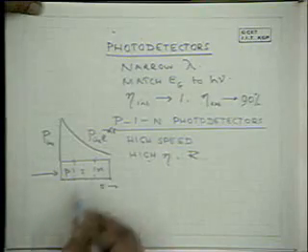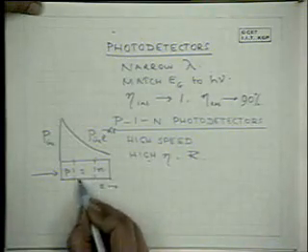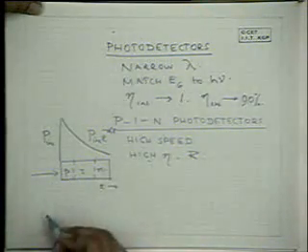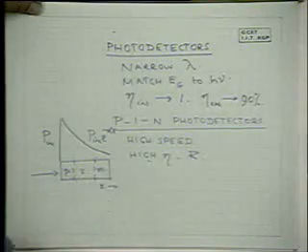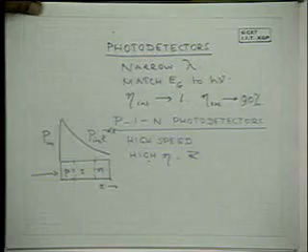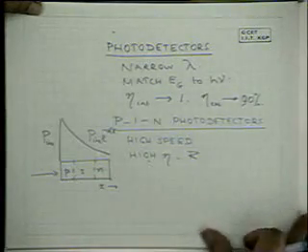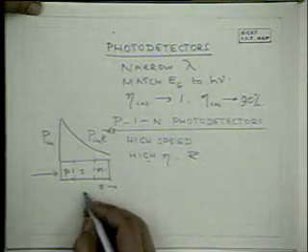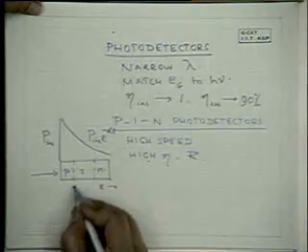The number of electrons created per photon would be low. Another advantage of this I region is that when this is reverse biased, there is a high field across this I region. If I draw the band diagram of a PIN diode, let me draw it again.